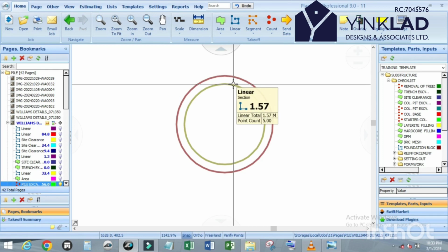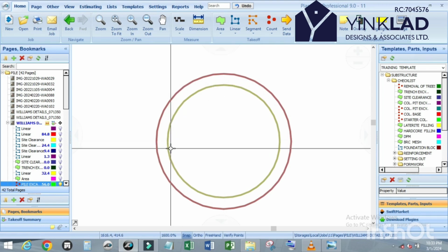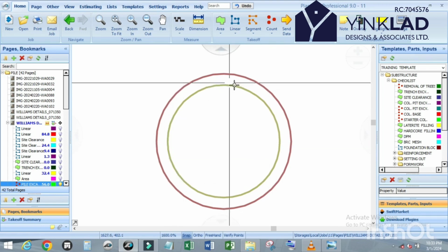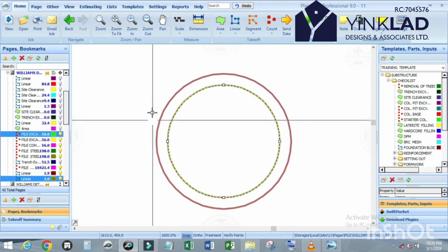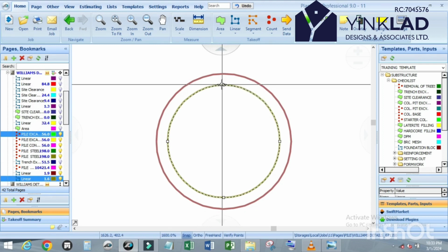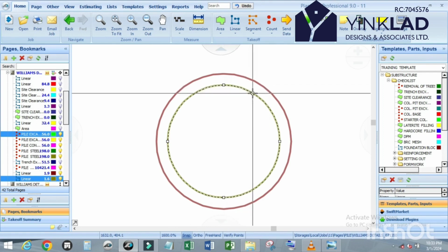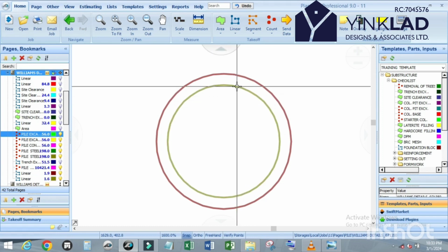So according to the lap that I explained for the main rebar, for example, if this stirrup is being deformed, starting from this point, now around like this, and terminating. For you to add the lap, as this one is coming, you can just bring it, adjust it, and just stop somewhere here, or anywhere, somewhere here. It depends on the length of the lap. So now, first of all, you are done with the stirrup length, which you have 1.57.